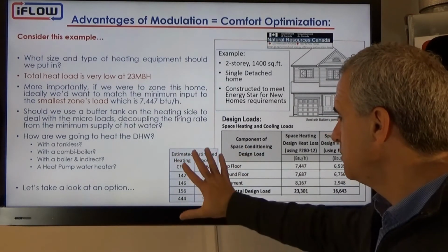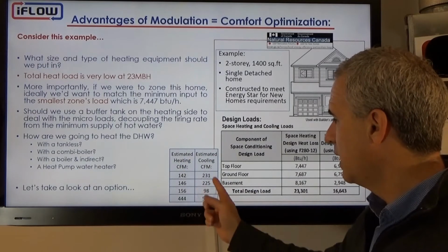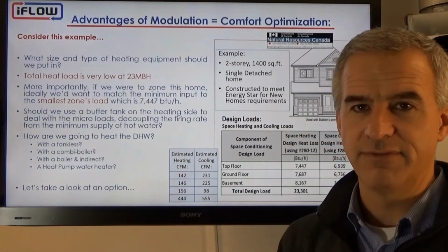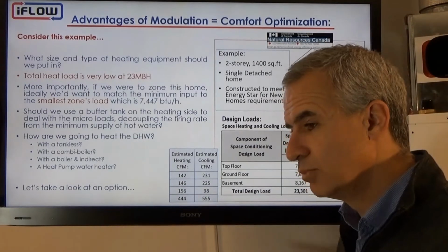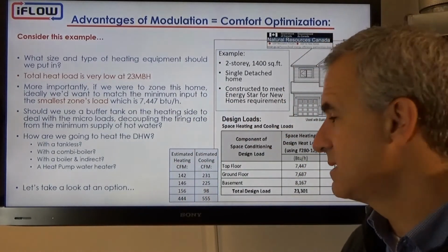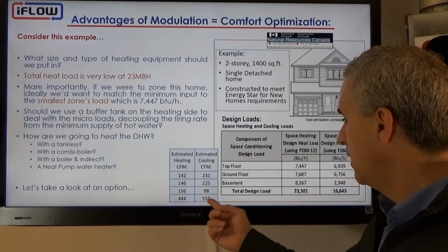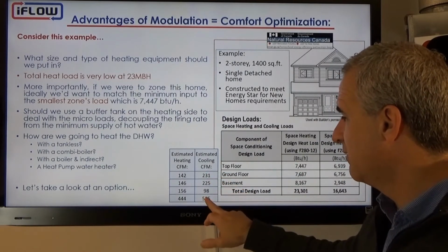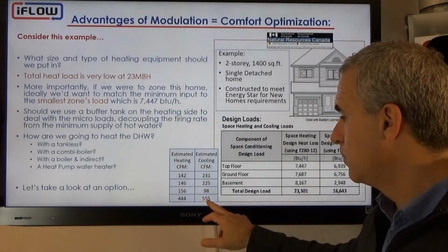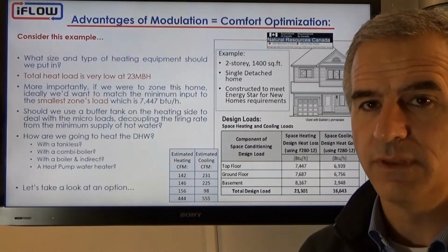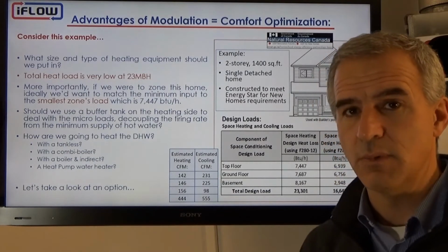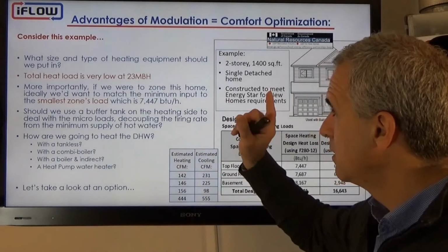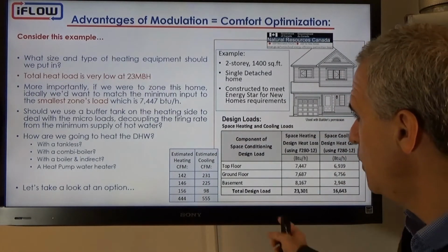So typically this would be very, very difficult to do, right? Many of the units have a minimum CFM of 400 or 500 CFM that they need to blow into that system. So that 4 or 5, that's maximum. So if I'm zoning this, there's no way I can effectively zone that. I'd have to run a bypass with all of the furnaces in the market at this point, for the most part. But with iFLOW, for example, we can do that.